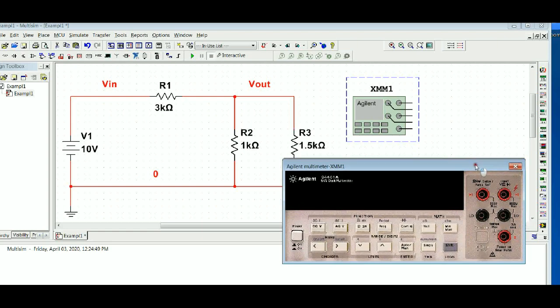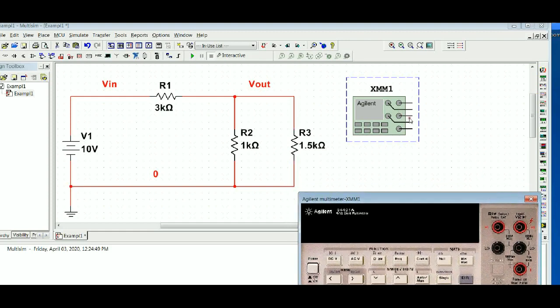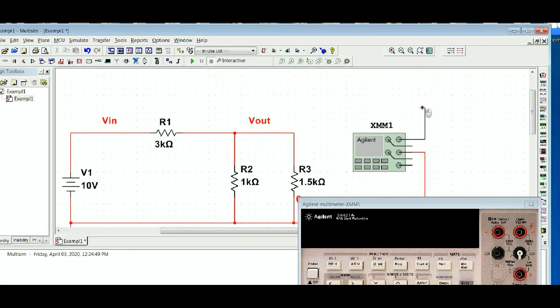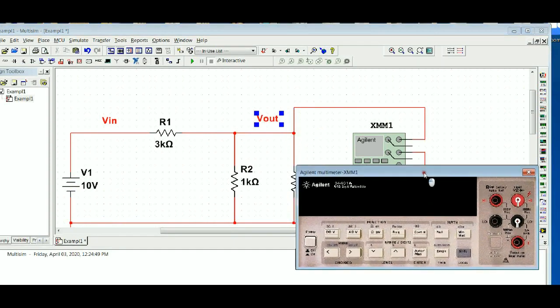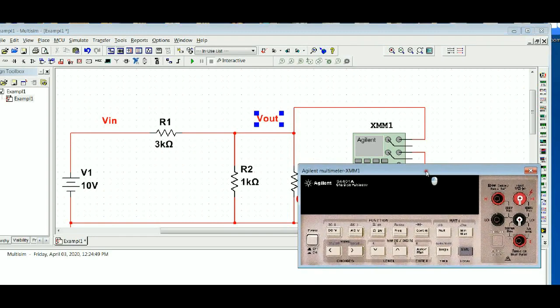So I'm going to do that to measure the voltage across this. I'm going to come out of my ground here. There's my bullseye. Oops, there he is. And come down to this point and go over and wire this into my ground. Then I want to come out of this right here and go over to my measurement point, which will be V out. Now notice I can connect this anywhere on any wire because it's all the same, connected by wires. So I'm pretty much set up with that, and I'd also like to measure the current flow, perhaps here.